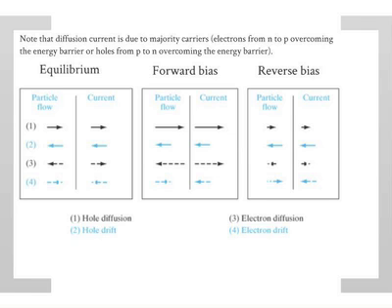So there are holes that got into an N side, N-type material. What happens to them? I can't imagine they'd last very long without being filled by electrons. Yes, exactly. They will recombine, right? So if there are a few holes and lots of electrons, they will recombine really fast. But not only that, they will diffuse, right? Remember we talked about steady state current injection. They will also diffuse. They will also move.